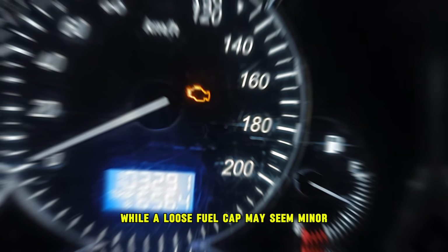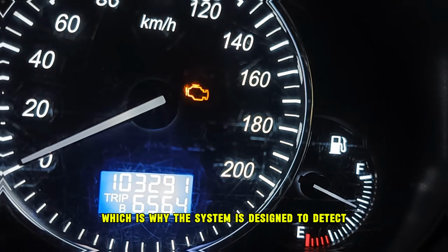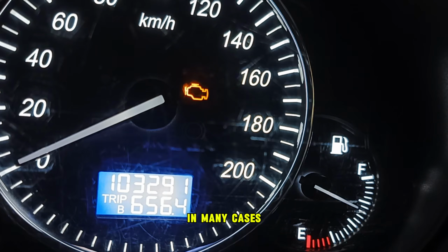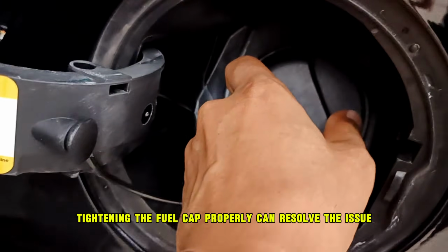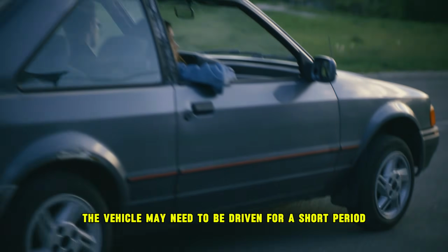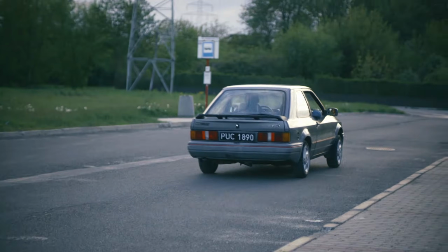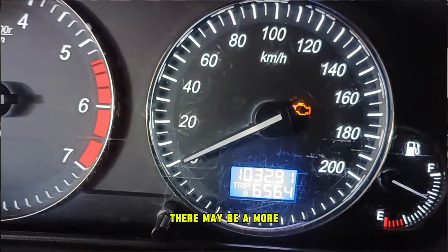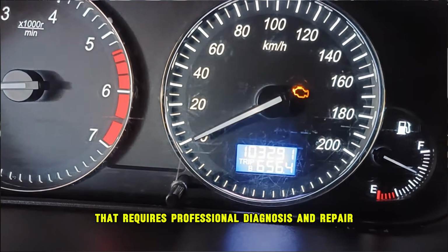While a loose fuel cap may seem minor, it contributes to increased emissions, which is why the system is designed to detect and report such issues. In many cases, tightening the fuel cap properly can resolve the issue. After tightening the cap, the vehicle may need to be driven for a short period for the system to recheck and reset the light. If the check engine light remains on after tightening the fuel cap, there may be a more significant issue with the EVAP system that requires professional diagnosis and repair.